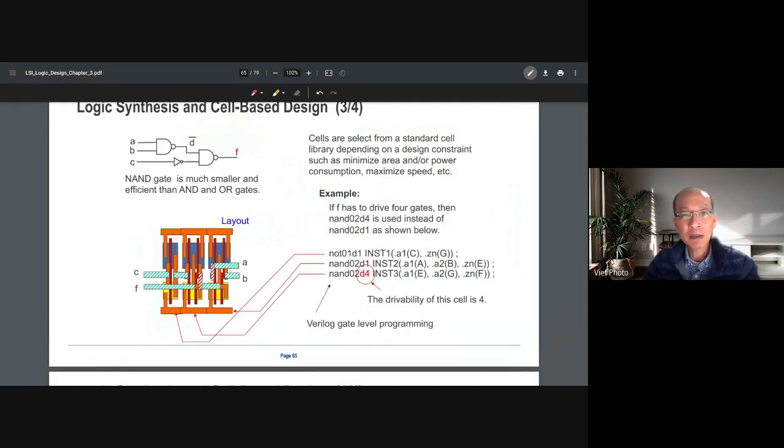Cell-based design, and then this one again, you have a netlist, right? And this one is a layout like this. This is supposed to be implemented on the layout on the chip, but that process is in the PD, not in the logic synthesis. At this step, logic synthesis, again I repeat, you have only the text file describing the cells and the connections between them. How it will be placed and connected, implemented on the layout, is the work of the PD.